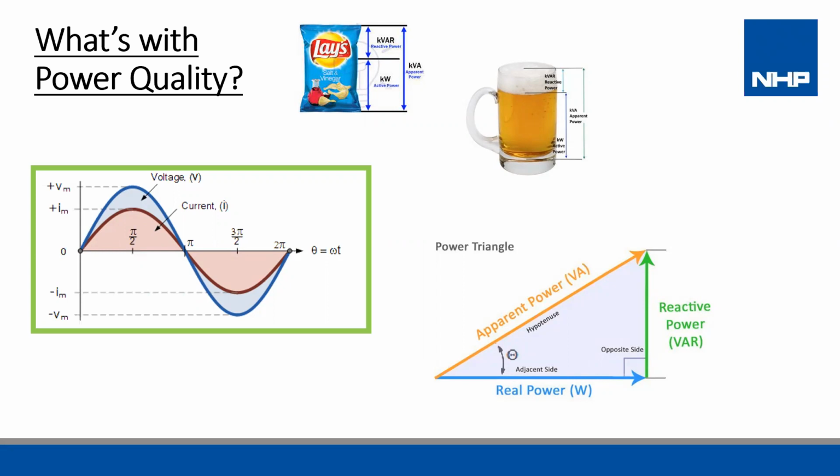In reality, the energy is just moving back and forth between device and source. But keep in mind, inductive loads like motors and transformers require reactive power to create magnetic fields to allow the work to be performed. Reactive power is also typically added by utilities as excess charges.